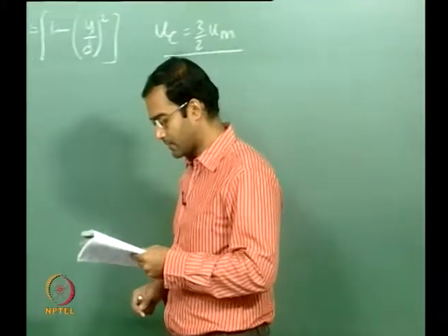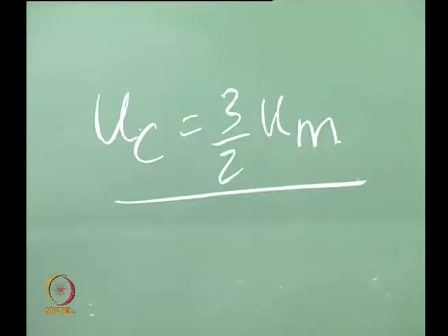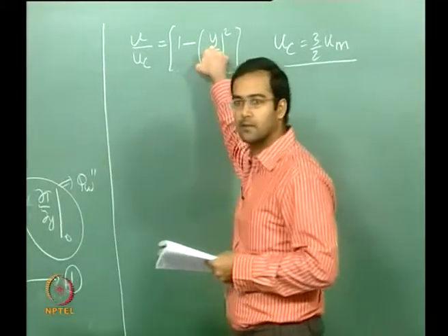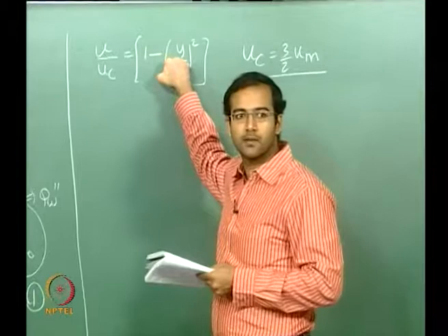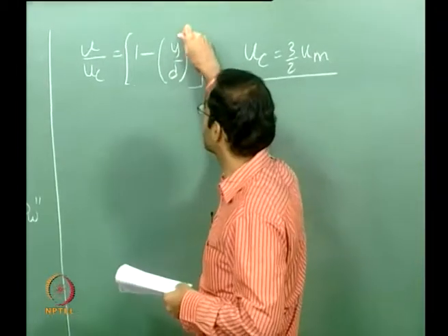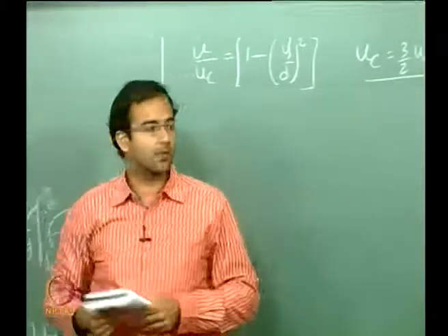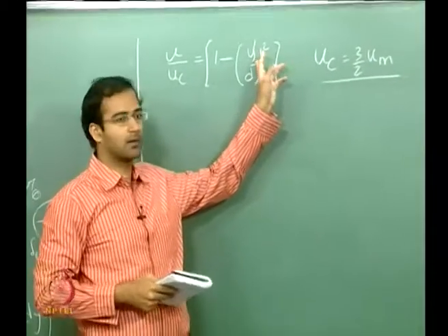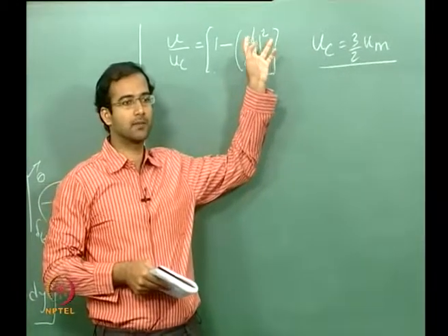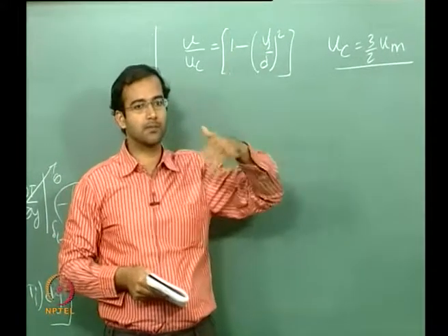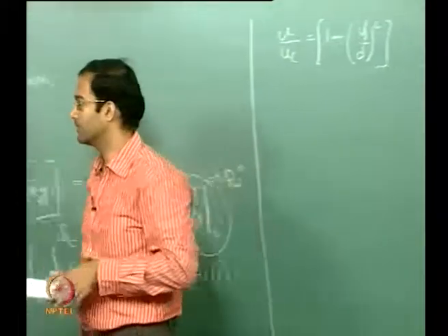So this is basically the velocity profile. Now this is written in terms of what coordinate system? The coordinate system for this is from the center, so this is y prime. If you look at the profile at y prime of d and minus d, then this will be equal to 0. That is only possible if the coordinate system is at the center.